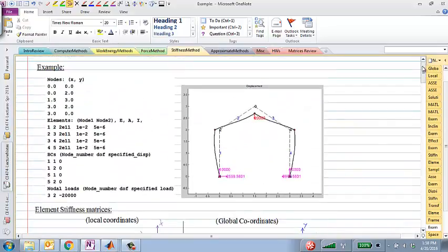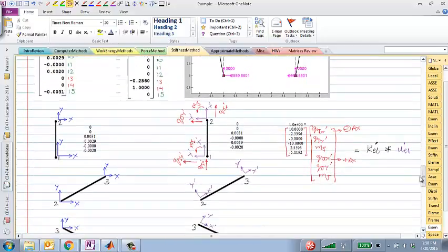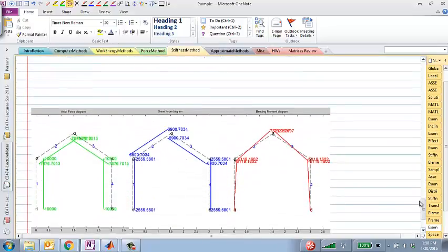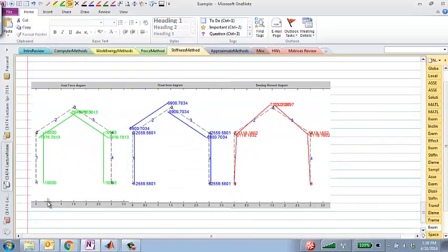And that also makes sense. If I have a load up here, this better be in compression. And since the total load is 20 kips, or whatever that unit is, 10 should be here and 10 should be here. So both of these should be negative 10 kips compression, which is exactly what we are getting. If we take the negative of that value and the positive of that value, we get the axial force diagram, which should be on your handout right here, minus 10,000 to minus 10,000 between nodes 1 and 2. That's how you find the axial force.